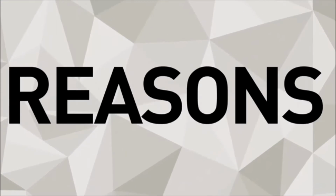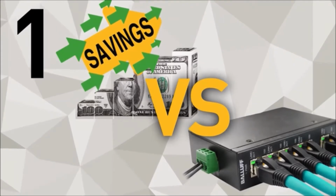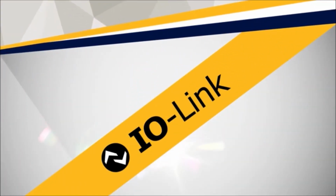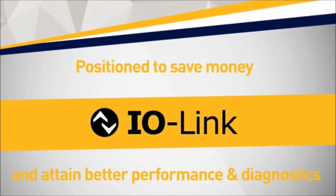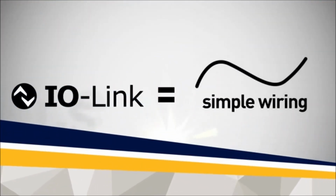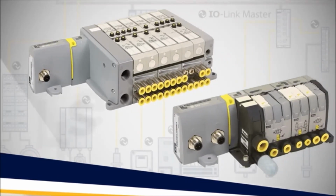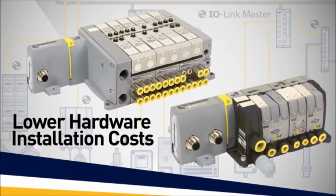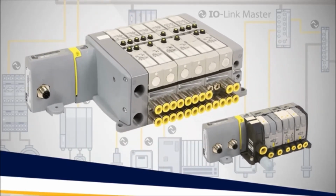There are two primary reasons to switch to I/O Link. 1. Save money versus using industrial Ethernet. 2. Attain better performance and diagnostics than hardwiring. I/O Link is cost-positioned in the middle ground between hardwiring and industrial Ethernet in situations where valve islands are connected to a node. I/O Link has the benefit of simplifying wiring like an Ethernet node on the manifold at a much lower cost point. We expect to see customers pushed to I/O Link for valve islands in order to lower hardware and installation costs versus industrial Ethernet and to get diagnostic data via a Class A or Class B I/O Link connection.